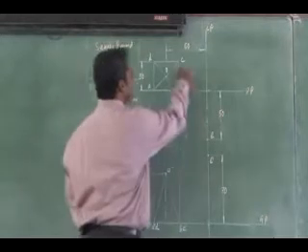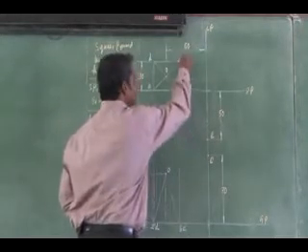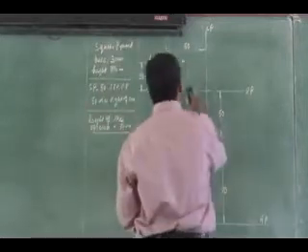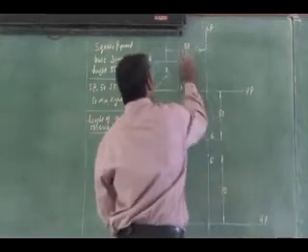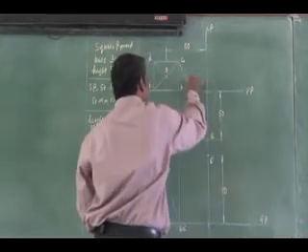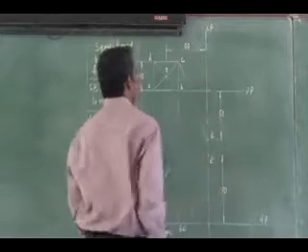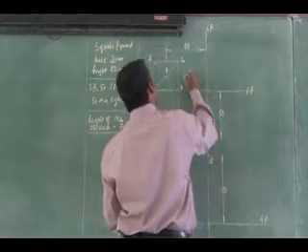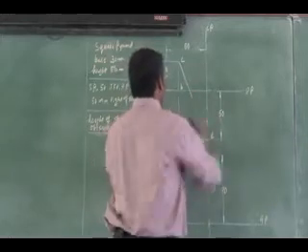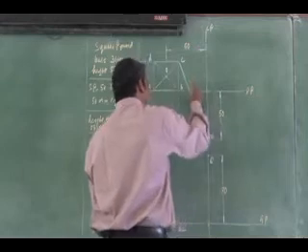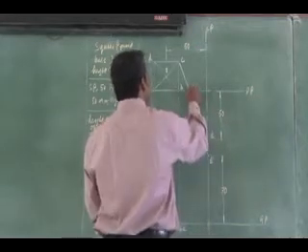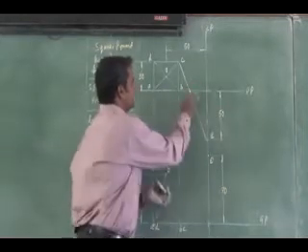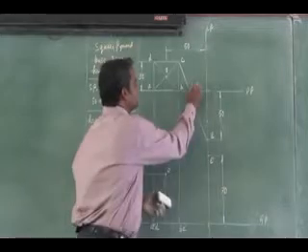Tell me what the intercept of C is. Suppose I join C to E with a visual ray line, drawing it to the top view corner C. Wherever it intersects, intercept means the intersection of the visual ray line with the picture plane. So this is my intercept of C.